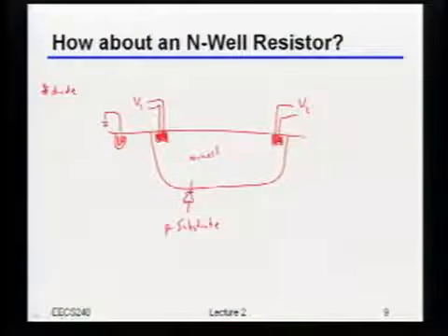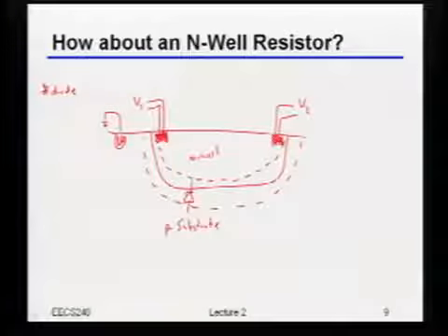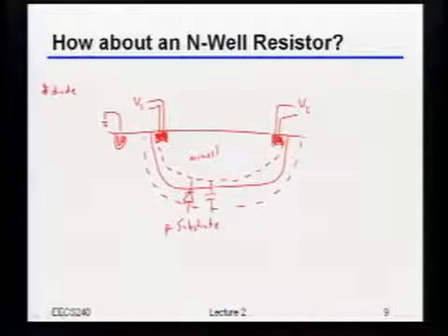So if I reverse bias it, that also means I'm going to have some kind of depletion region here, right? So as you also mentioned, if I have that, that means I get some capacitance. Now, why is capacitance kind of bad in this context? Why do I not want capacitance? RC charging slows down. Yeah, so everything you said was correct. You said it's RC charging, it slows you down.